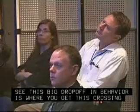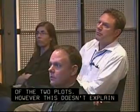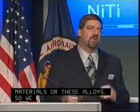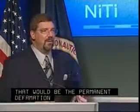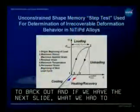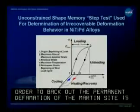However, this doesn't explain necessarily why you get this irrecoverable strain in these alloys. And so we forgot one component to this, and that would be the permanent deformation behavior of the martensite phase. And this is a little bit harder to back out. And if we have the next slide, what we had to do in order to back out the permanent deformation of the martensite is go through and do these step tests doing shape memory behavior on the material.